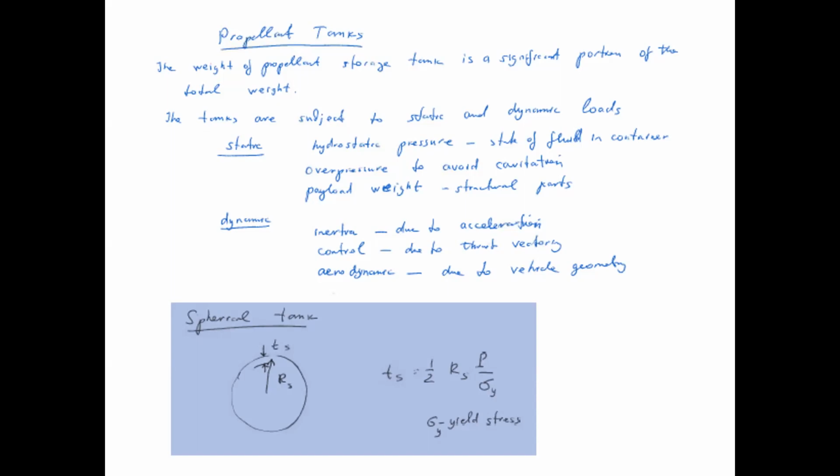Static load is basically dependent upon the fluid in the tank. That creates a hydrostatic pressure, and it applies force towards the wall of the tank. So that is your pressure times area.